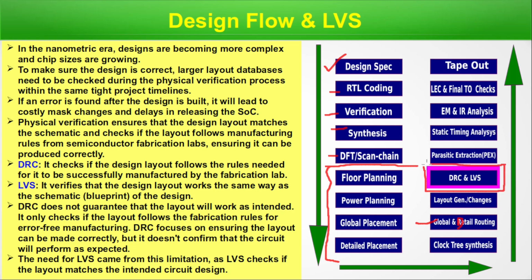This is basically backend verification. DRC and LVS, we always hear these two terms very closely. They are always uttered together. DRC means design rule check and LVS means layout versus schematic. These are very basic and important steps of backend verification, along with EM and IR.